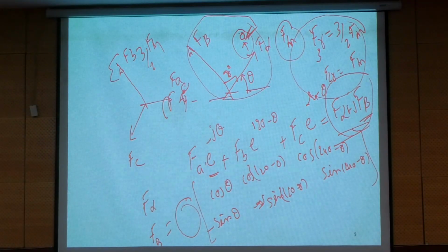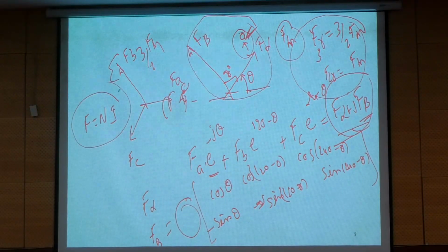1.5 is the difference. You got my point? So there is a difference, net MMF. If you balance, if you take care about this one, the important thing is MMF is nothing but number of turns into current. You need to take care about the current magnitude as well as turns ratio. By taking care about the turns ratio and current magnitude, we can maintain constant MMF after conversion also, right?